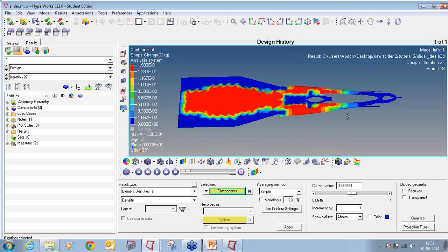So this is the area from where you can scoop out the material. If I change this, I'll enter, say, 0.3 or 0.5. So in this way you can remove the material as well as create the bead patterns. So both the things you can do simultaneously with the help of this.